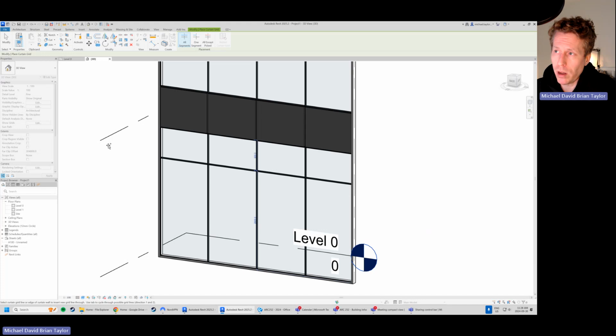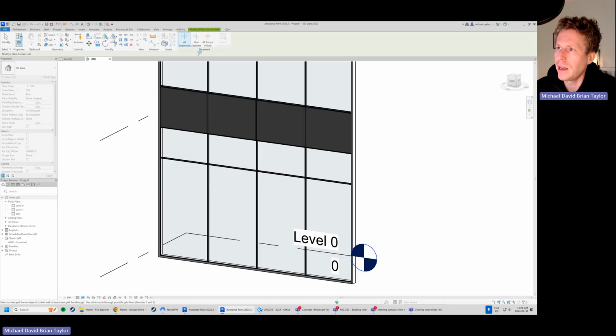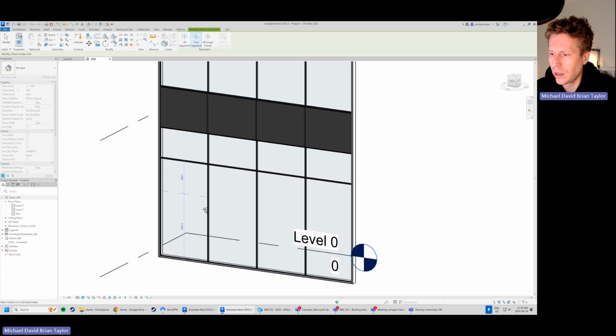One thing we might want to do as well is do one segment instead of all segments. I've got all segments selected right now, so it's going to do across our whole curtain wall. I want an entire piece, right? So vertically, if I click this, it's going to give me that whole wall, that whole height. For one moment, I'm going to undo that. I just want to do one piece. Watch this. So if I just want to do one piece, click that. Say we got maybe a little Siamese connection or fire department connection down here.